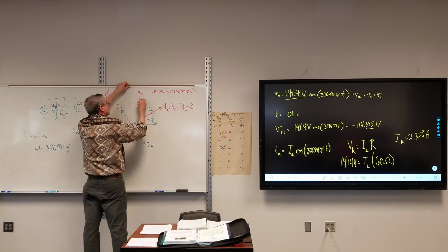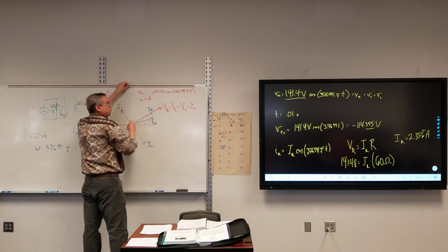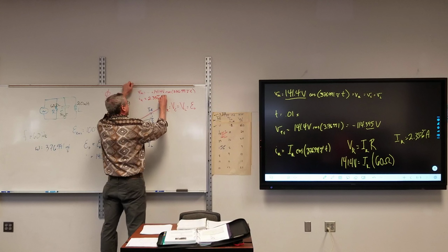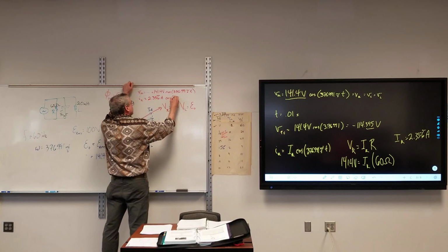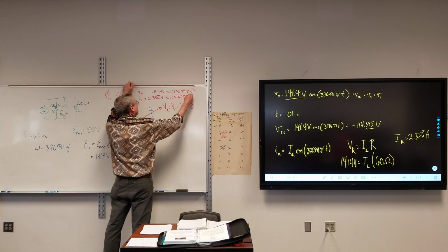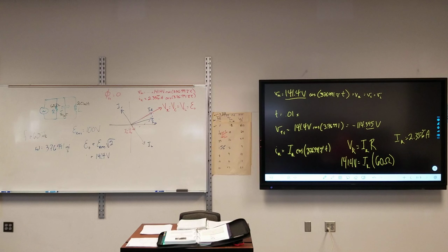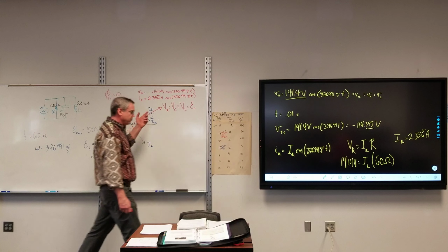And the current for the resistor is 2.356 repeating amperes cosine of 376.991 radians per second times time. Oh, never mind, I just realized that we were all solving for big I and not little I. Yes. But in finding big I, we know what little I is. Indeed. We'll do the power supply last.